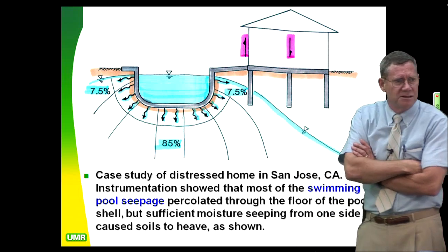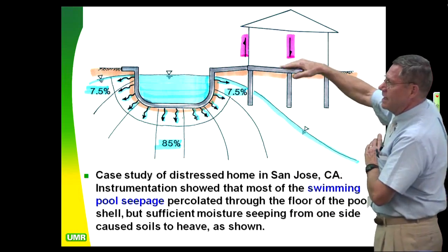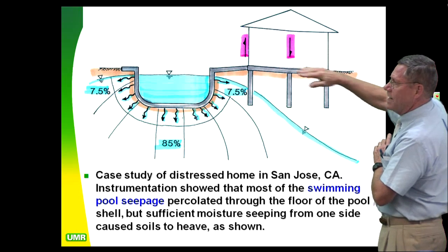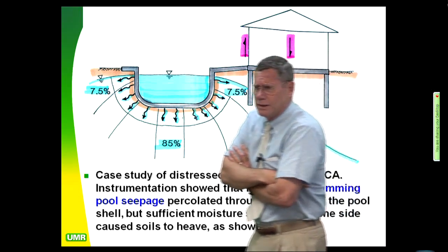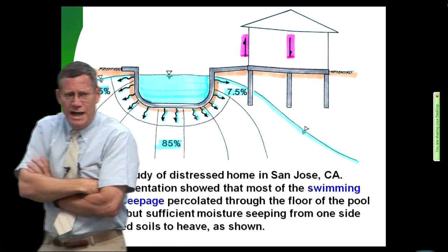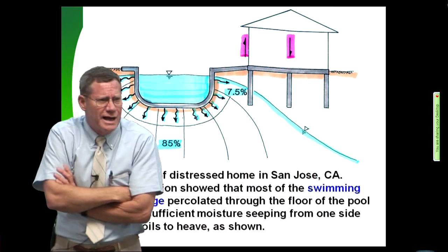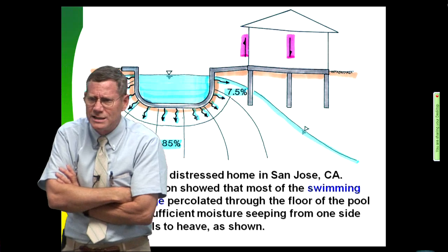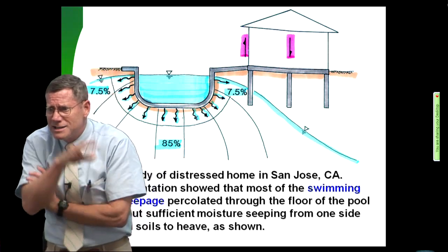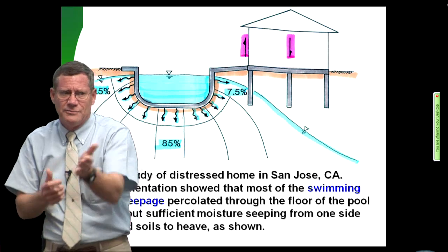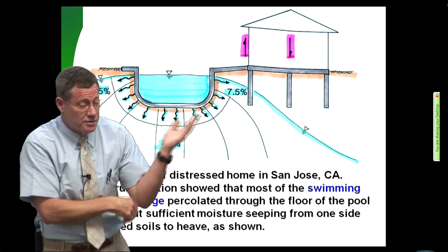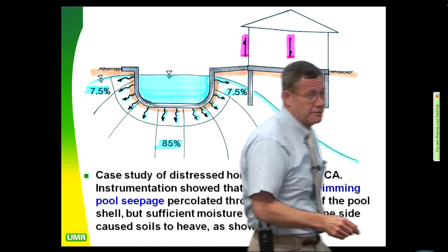You dry pack the mud sill. You jack this up, dry pack, jack that up, dry pack, bring it all back up level. I haven't heard from him since 1984. As far as I know, he's doing fine. I did tell him, if you drain the pool, Smiley, for more than about 6 or 12 weeks, this ain't going to work, because that side of the house is going to settle. And we added that as a restrictive covenant onto his deed. I'm sure he's retired and moved on, but haven't heard from Case.